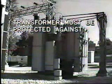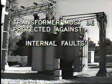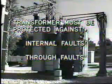The transformer must be protected against internal faults and through faults. Internal faults occur as a result of insulation failure, which creates a short circuit path between phases and often to the grounded iron core. The heavy fault current flowing can cause serious damage to the windings and even burn the core itself. If an internal fault does occur, the transformer must be immediately switched out of service and isolated. Differential protection provides the best protection against internal faults. And we'll be discussing this in detail in the next segment.